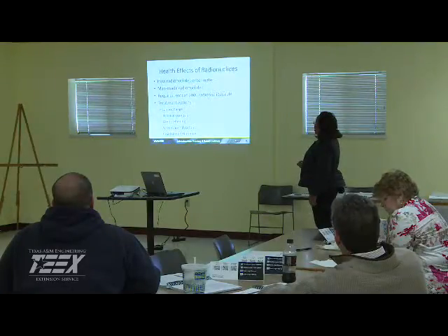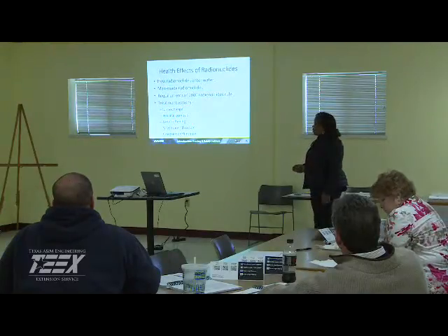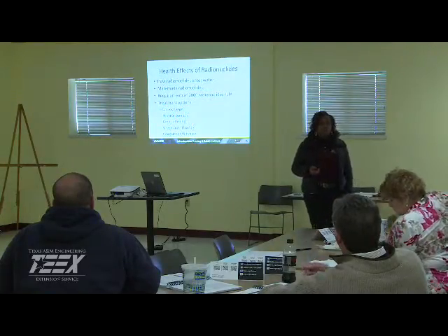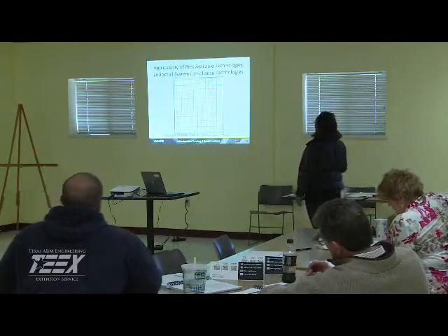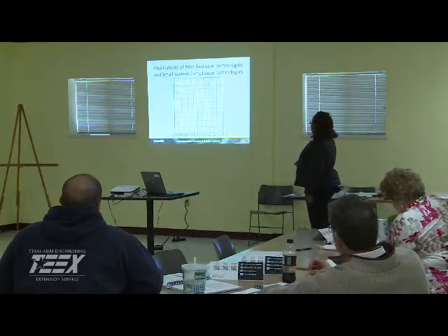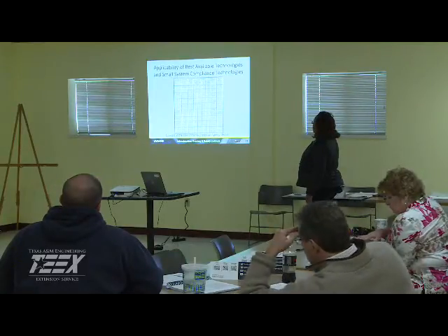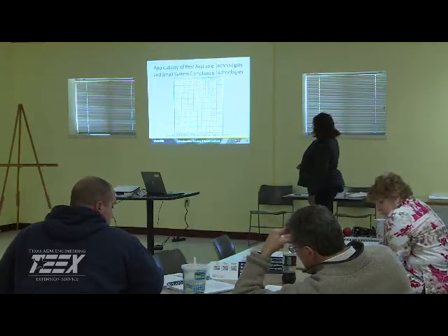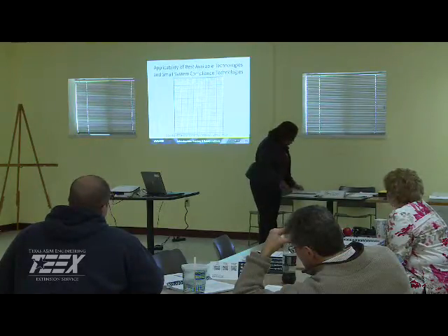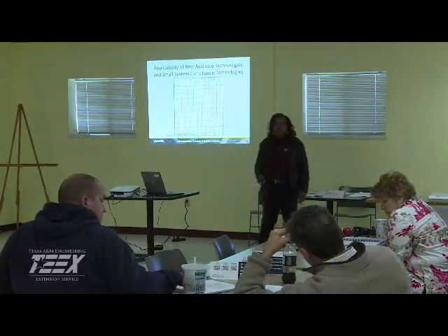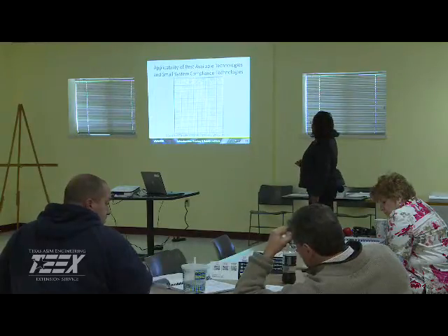So, treatment options: we have ion exchange, reverse osmosis, lime softening, green sand filtration, and coagulation along with filtration, all possibilities for removal of these radionuclides. And that's what this particular chart is, simply telling you the best available technology to remove the various contaminants. This one is in your book on page 8-8, if you want to refer to it at a later date, because I know you can't read it up here.